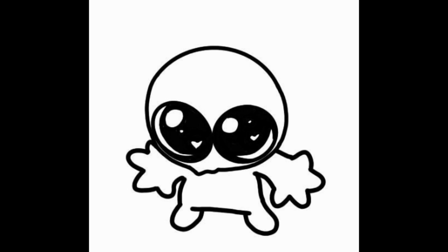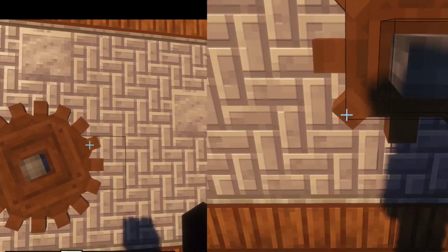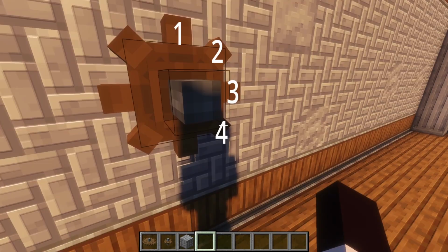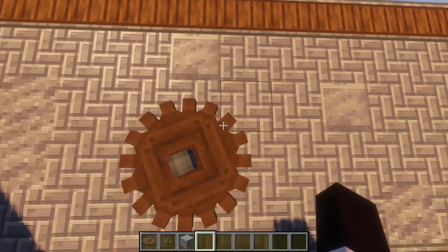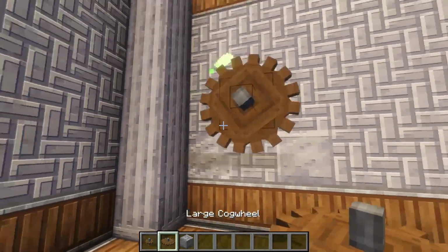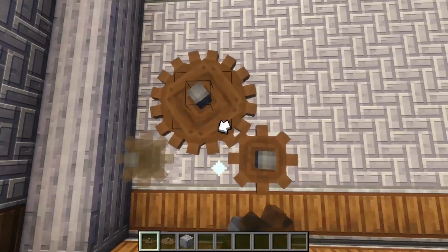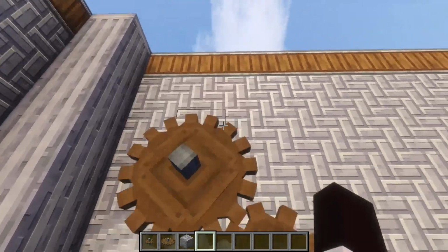And one detail that I want you to put in your cute little brain, that'll be very important by the way. Cogwheels, the big one and the small one, are exactly double the size or half the size of each other. So this means that the small cogwheel has 8 teeth. And if you look at the big one, it has 16, it's exactly double. Keep that in mind, okay? Why is that important? For every single complete rotation that the big one does, the small one has to perform 2 spins and vice versa.